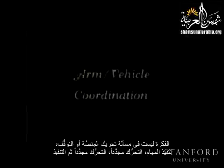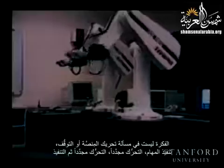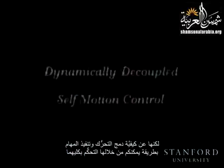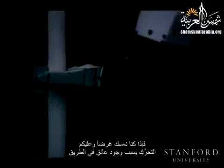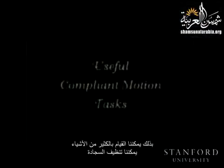So the idea is really not to think about the problem as, well, moving the platform, stopping, manipulating, moving again, stopping, manipulating. It is about how you can combine mobility and manipulation in a way where you are controlling both. So if you're holding an object and you have to move because of an obstacle, you should be able to decouple the two. We call this the task, and this is the posture. And we are able to control the whole robot to achieve a task and also to achieve the posture in a decoupled way.